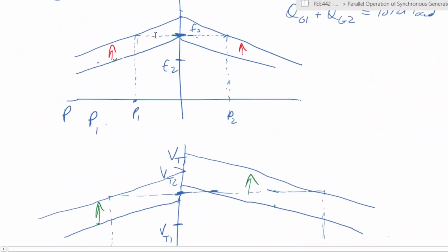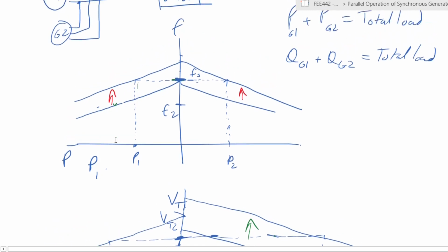Yeah, if you have them back to back like this, you are seeing the way I was moving around the ratios and increasing the frequency. Graphically, that's how you would do it. The example that I've talked about now puts that mathematically so that you can use the slopes of each, because these slopes, these values of SP, you will generally have the value. So for example, say, 1 megawatt per hertz or something like that, X megawatts per hertz. Okay, so now when you're comparing the two of them together, this graphically represents what you're talking about. And second part of the question, also one to be lagging and the other to be leading.